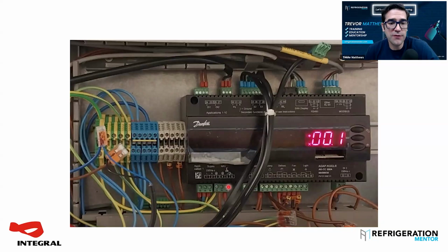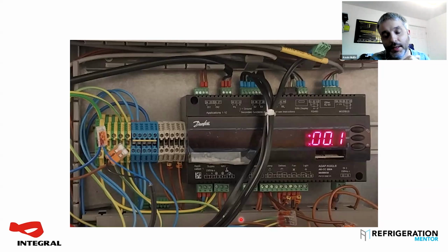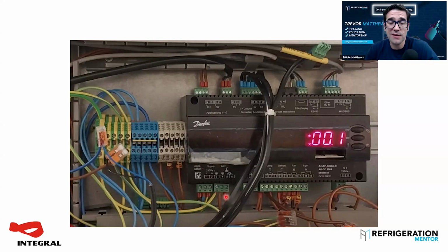And you're going to need to replace the coil. And so you can do it from the controller, but just remember, you've got to unplug it. And if you do it from the controller, there's resistance in these lines. So who knows how long these lines are running, right? Absolutely. So the best thing to do, if you get weird resistance from here, you've got to go right to the coil itself.